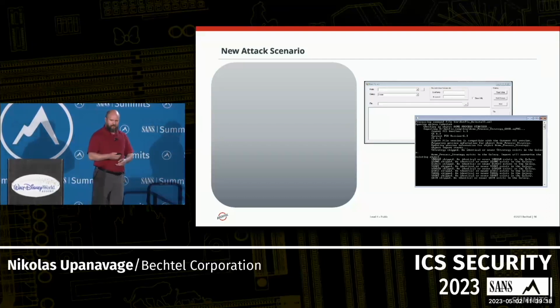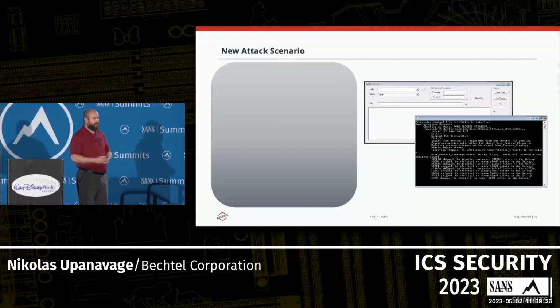But we found that you can take a logic backup of the existing logic that's on a controller. You can plug it into a separate system that's running that same integrated development environment, modify that logic, and basically take it back in. So I'm going to focus primarily on the part where we're changing the control logic itself.